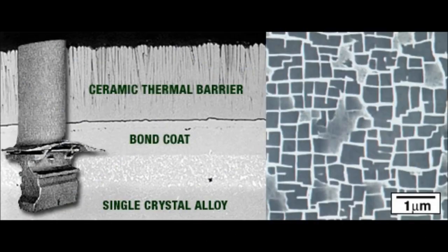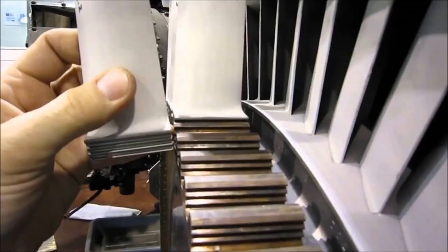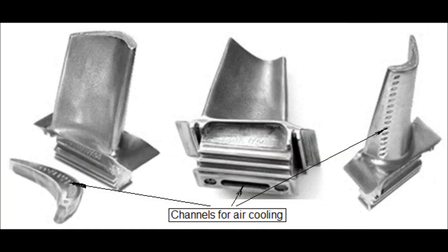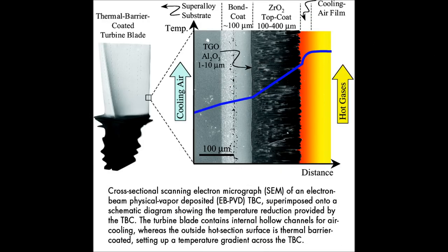Even greater than the aluminide coating, ceramic thermal barrier coatings were being applied to the blade, starting in the early 1980s. This coating is applied to the outside of the blade and increases the blade's ability to endure heat by 400 degrees Fahrenheit. The final addition to the blade was an air cooling system. This is a series of holes in the blade, allowing for air to flow through. This cuts down on material usage, and the airflow helps to cool the blade.